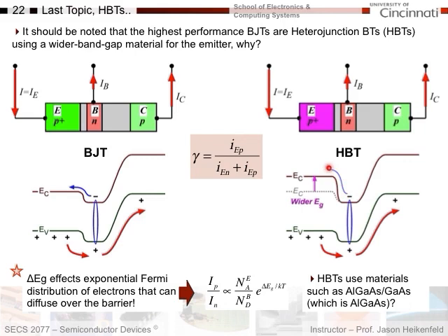If you want to, and of course this gives me a better emitter injection efficiency. Again, emitter injection efficiency, I want all holes and no electrons, so of course it improves my emitter injection efficiency. If you want to calculate how much this helps you, it's actually pretty easy and it makes sense. And so we've already shown, and you did this in our homework in the past lecture, we've shown in the previous lecture as well, that my hole current divided by my electron current is proportional to the ratio of the dopants, right?